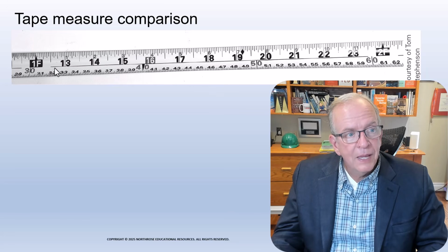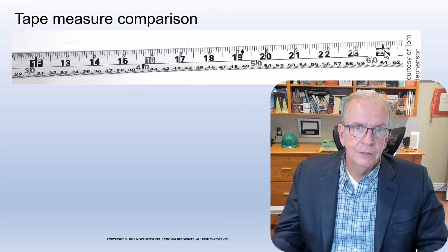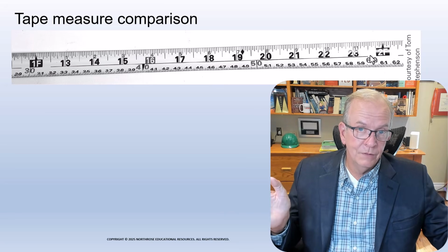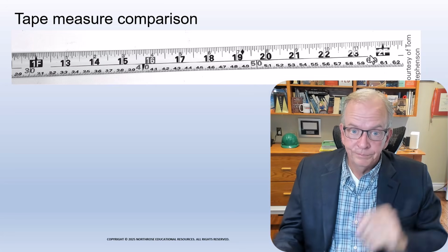Our standard spacings all divide evenly into 8 foot. The most standard spacings are 12, 16, and 24, and they even divide evenly into 4 foot. So basically the width of a sheet of plywood as well, or drywall.